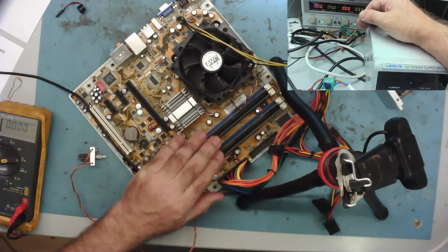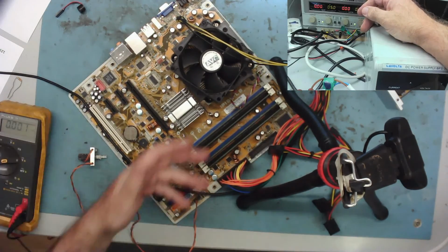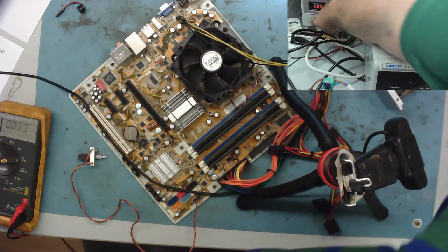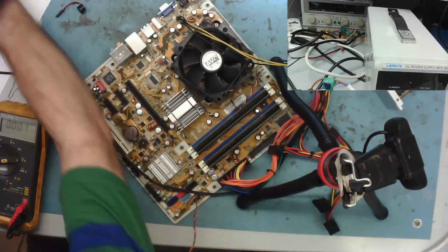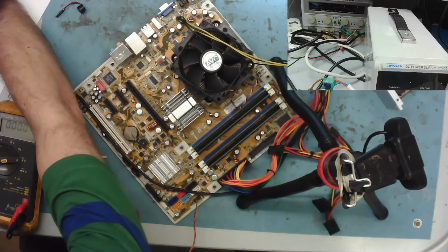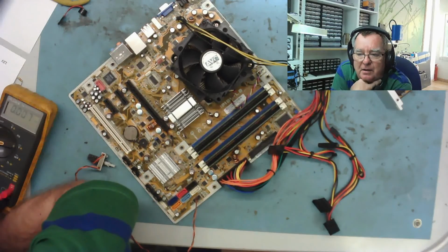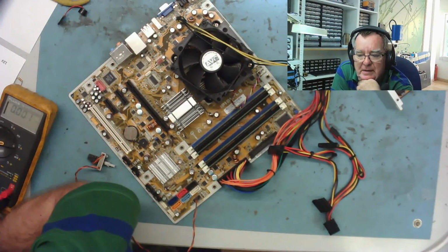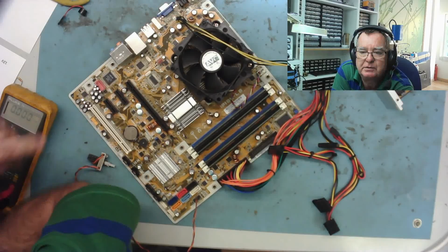I can just stick this onto a normal power supply as well, but I can't really measure the current. I mean, I know the board works anyway. So that wasn't exactly totally successful. Not the idea, but the power supply isn't powerful enough. Obviously then I need another way to test that faulty motherboard. I was hoping this was going to work so I could effectively prove which rail was drawing more current if I compared it with the working board.